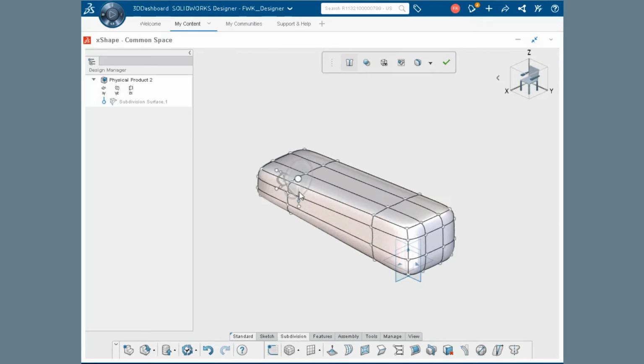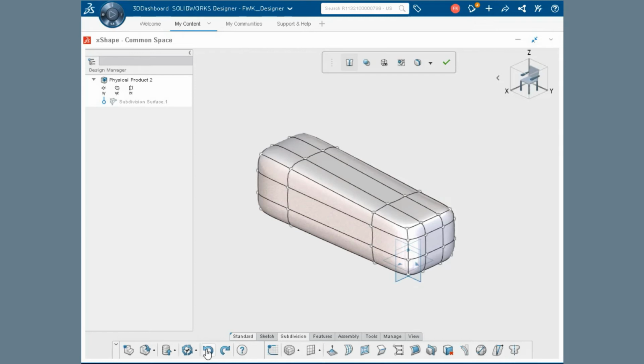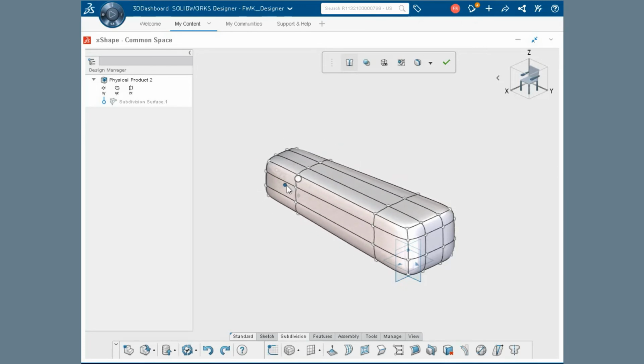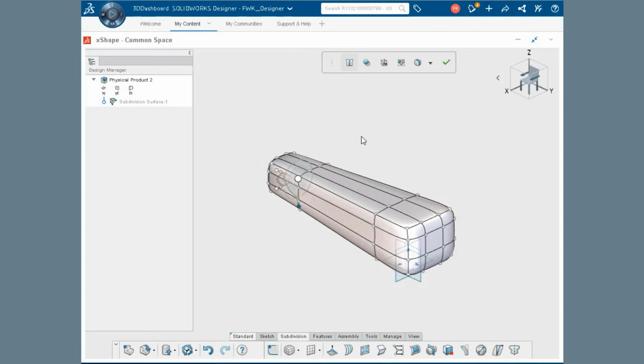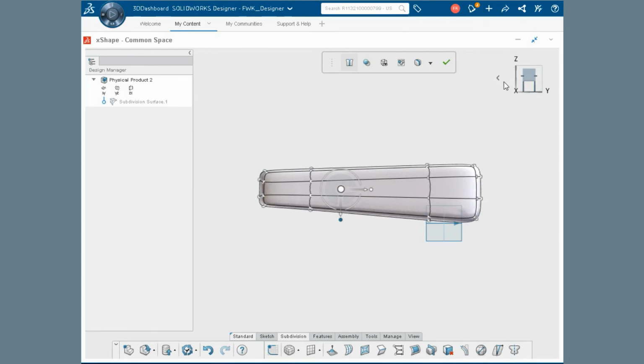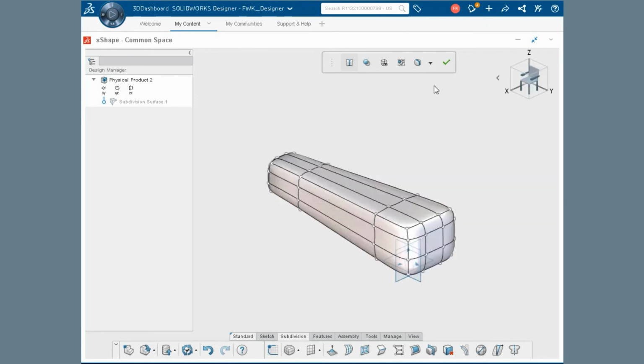That isn't what I wanted, so I'll click Undo or press Ctrl Z to undo that change. I'd like to scale the same amount in 2 directions at the same time. This is useful for a box and also for shapes like cylinders and cones. I'll select the face loop again, but this time I'll click one of the scale handles to highlight it. Then I'll move to the other handle in the plane that I want and push it inward, shaping the geometry and keeping it square. Note that the highlighted handle may stay selected, so you may have to click it again to turn it off if you don't want to use it.